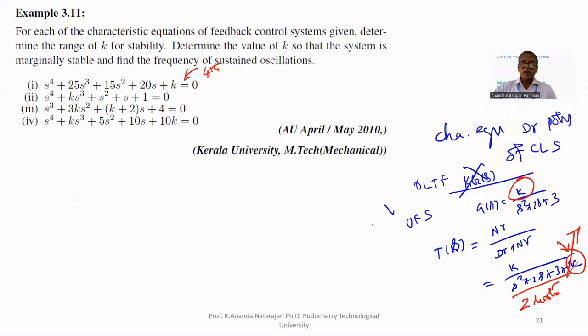No system in the world is first order or second order. All systems are more than second order. Your bike that you are riding is third order onwards. If you increase gain, the poles on the left hand side will move very close to the j omega axis. So if any disturbance comes, you will oscillate. You can notice that when the speed is very high, you cannot take decisions. It will oscillate because the poles are very close to the j omega axis. That's why speed is dangerous.